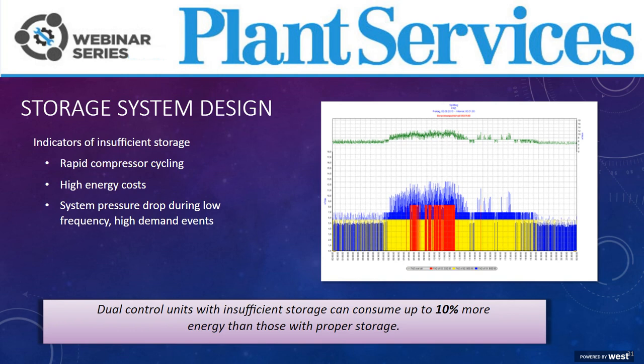You may not have enough storage in your system if you notice your compressors are rapid cycling, or they have higher energy costs than expected, as well as if system pressure drops during intermittent high demand events. Keep in mind that this is worth fixing, as dual control or load/unload units without proper storage will consume up to 10% more energy, and that's a minimum number. You also have to consider the reliability of those units and the service costs without proper storage.